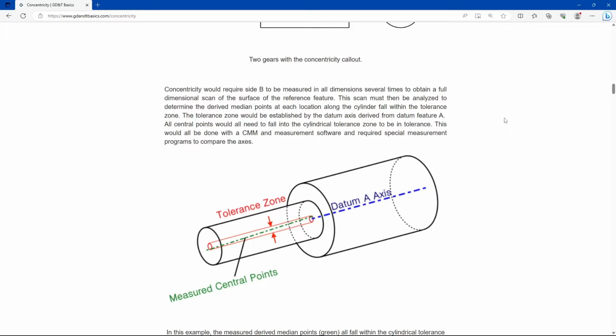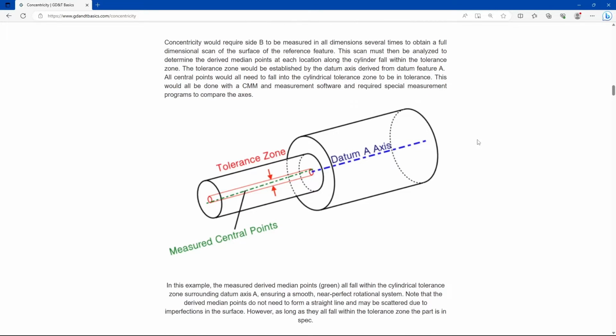It's always a guess from the CMM, touching the points on the outside of the job and then trying to work out whereabouts the central point is based on those external points. So it's always been an issue that concentricity is like a theoretical center point from data points taken on the outside of the feature. This alone obviously causes a lot of discrepancy between different software packages that use different algorithms.